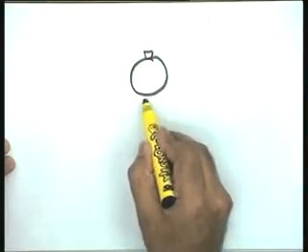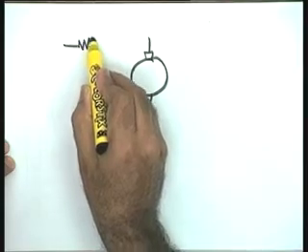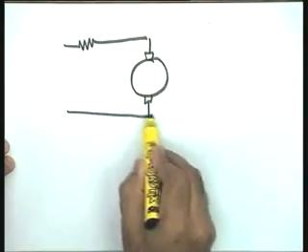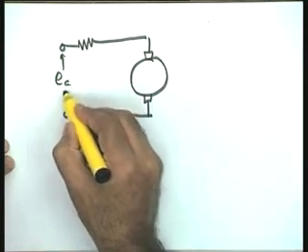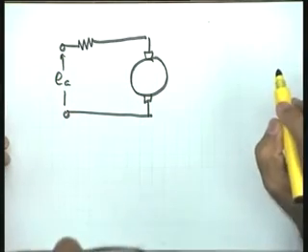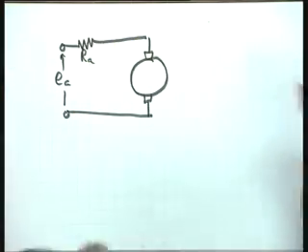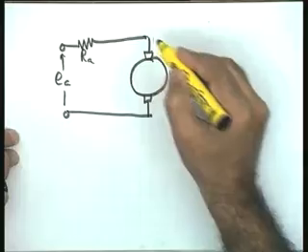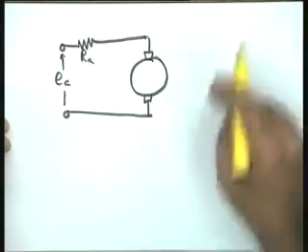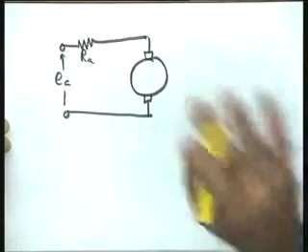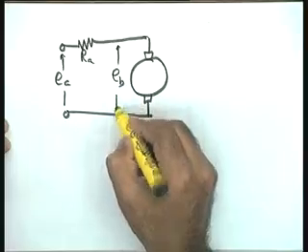So, now again you take the motor, some newer points, some points will come which have not been covered in the last lecture. I had taken this as an armature controlled motor. So, in this particular case, the control variable is the armature voltage EA. I had directly neglected the armature inductance, because this is usually the case. In the approximations which we make in modeling, the armature inductance is normally neglected. So, I have not included it right in the beginning in my mathematical model. So, EB is going to be the back EMF on this.